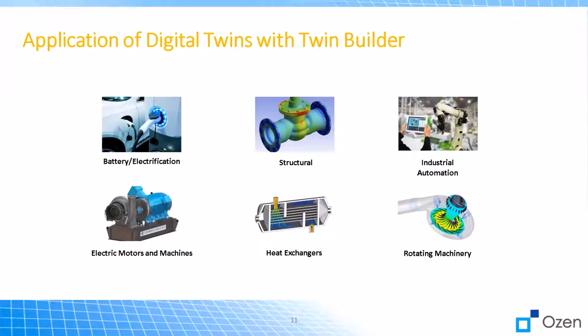All of this physics we can use. You can create a digital twin and use Twin Builder to create this twin model and help us in the predictive maintenance and understanding the system in better way and get results for that doesn't have sensor available for it, or it's hard to measure it in real life.